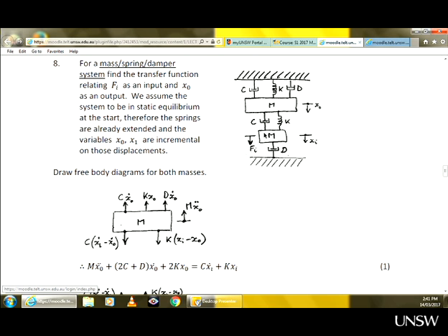On the other side, you have these two forces pulling down. So this force will be equal to c times the relative velocity between this point and this point, which is xo dot and xi dot. So xi dot minus xo dot. I expect a question here. How do we know it's xi minus xo, not xo minus xi? Because someone asked that in one of the tutorial classes when I was there. So you have that question, or you have the answer. Okay.